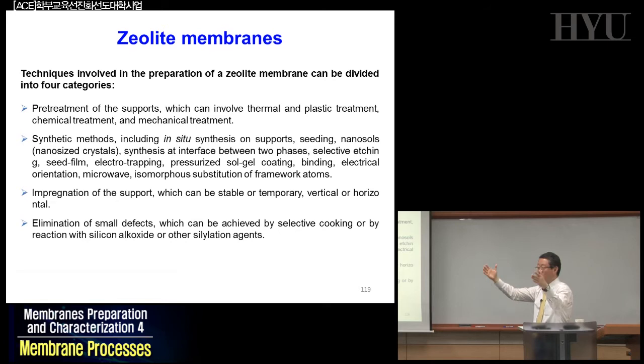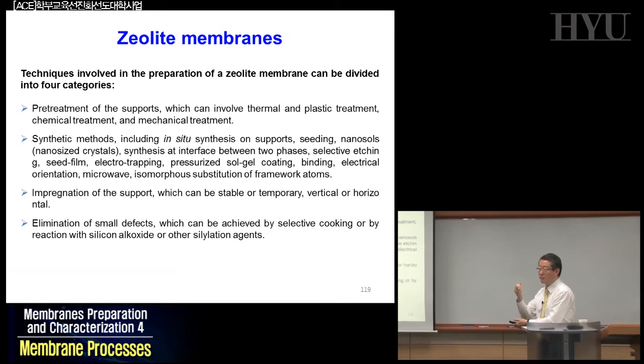Plate and frame type modules in a vacuum, and zeolite membrane right now could be utilized in pervaporation membrane systems, where you pull the water from your aqueous system so that you can concentrate your organic solutions, or you can pull the organic compounds out of your aqueous solution, so that you can concentrate your organics out of those hydrophobic or hydrophilic membranes.